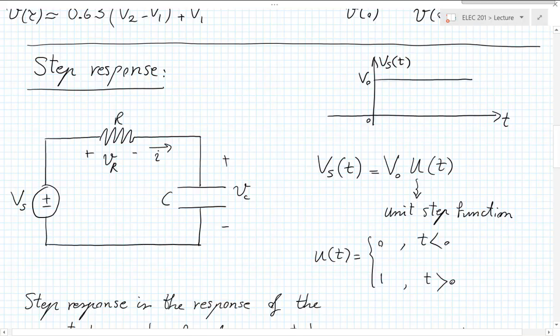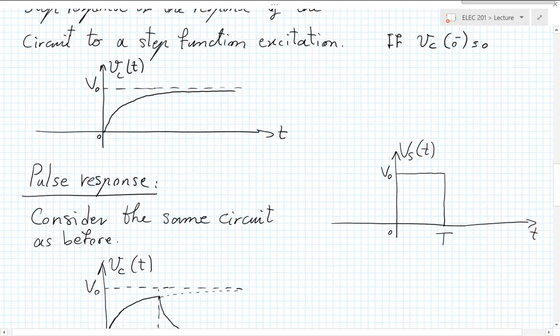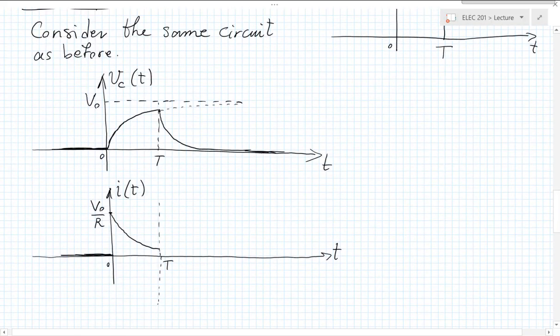So at t, we said that the source becomes 0 all of a sudden. So all I have now is the voltage of the capacitor dropping across the resistor, and that tells me the current. So I need the voltage of the capacitor at that point. It would be useful to maybe write the equation for this. So if we are describing Vc of t, what is the formula for it?